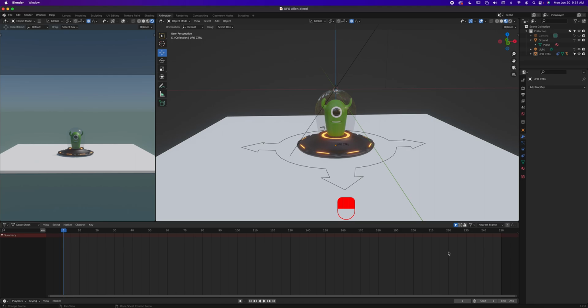We start off in Blender by default at 24 frames per second. So 1 second takes about 24 photos or shots. That's kind of like our timing, 24 frames per second. By default, Blender starts at frame 1. So to make up 1 second worth of animation, it'll be 1 to 25 right here, which is 24 frames. If you opt to start at 0, because you can change your start time to 0 right here, that'll be 0 to 24.